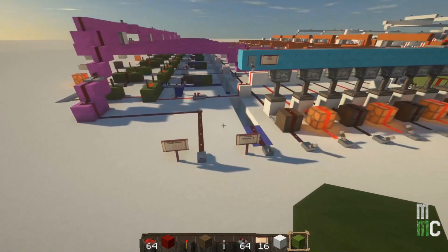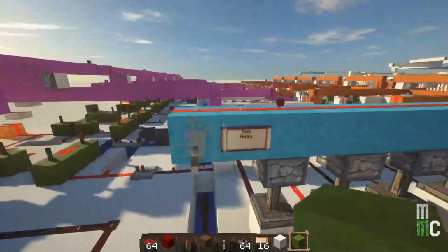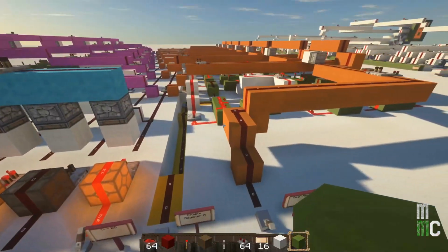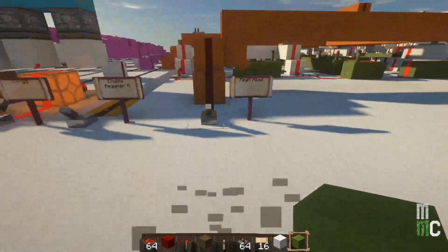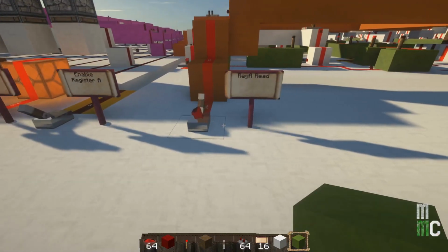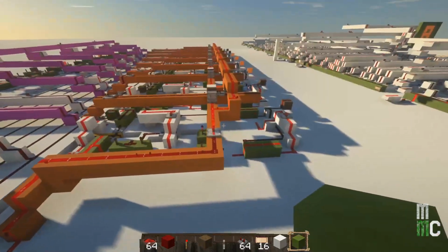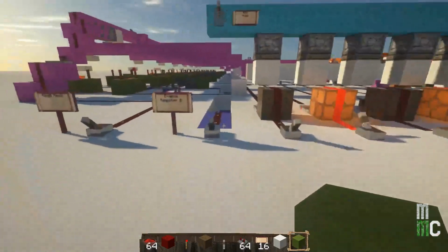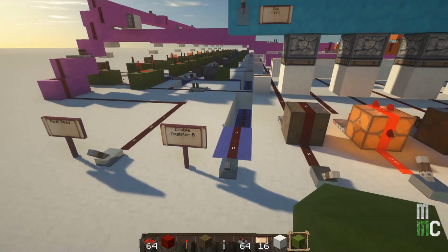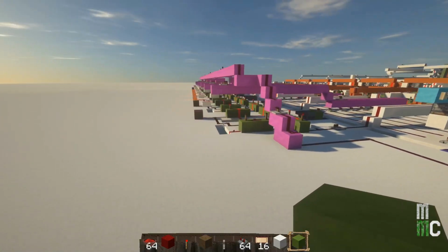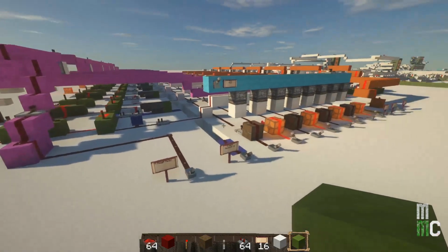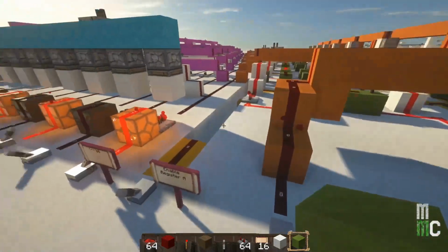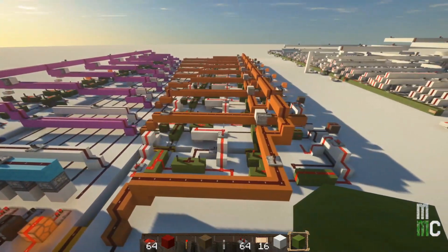Now, what if we're going to go register to register? First thing we have to do is turn off the bus value, so there's no value on the bus. It is empty, got a 0 on it. And we now want to say, let's go from register A to B. We want to read this value. Remember, it is 2 off, 4 on, 2 off. That is now on the bus. All we have to do is come over here and enable register B. And we now have the same thing. 2 off, 4 on, 2 off. So we've moved the value from A to B. Of course, the last thing we have to do is turn off this read. And we now have the 2 registers being equal.